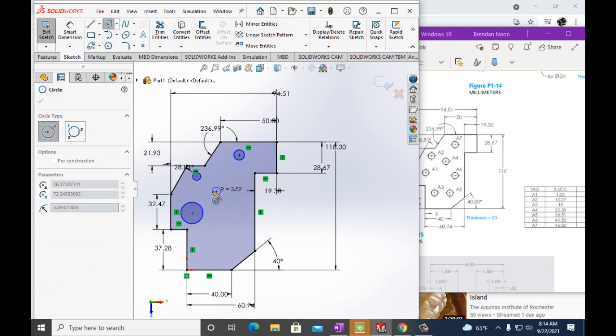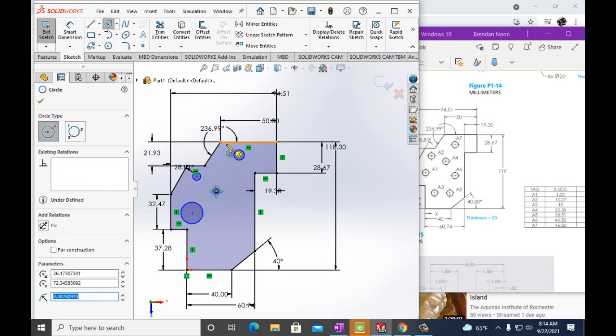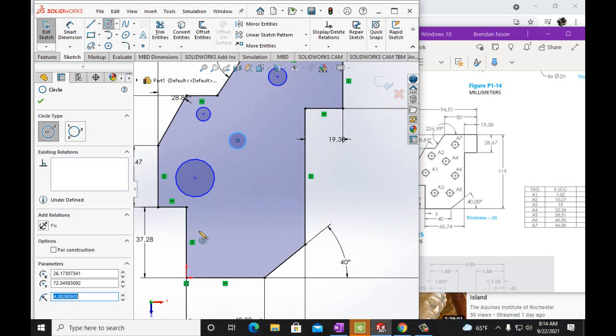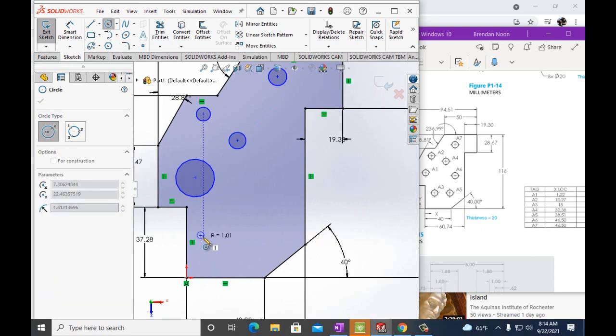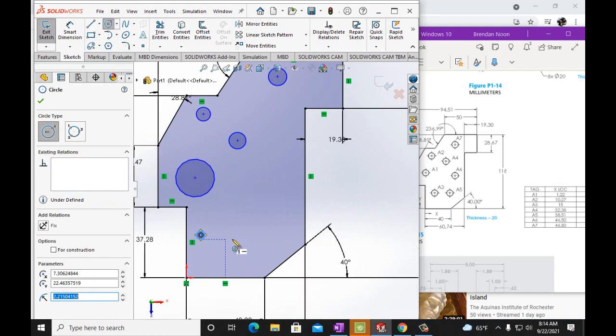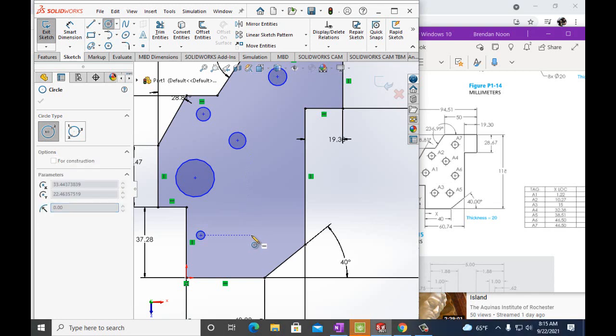Now I don't want to get those dash lines. I don't want those on my circles because I want to move these around. And then we got 1, 2, 3 coming over here. So I got one. The more you draw, the more difficult it becomes to not get these blue lines. So you find a point where you don't get a blue line, and then just draw the circle. And then I think this one's all the way across here somewhere. That looks good.